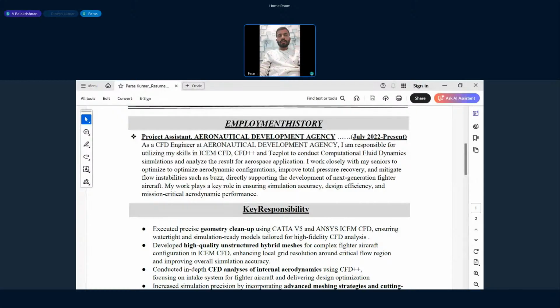Yeah, it depends. It mainly goes to the mass flow rate, like whether the engine wants more mass flow rate or less mass flow rate. So sometimes when the engine demands less mass flow rate and we are giving more, it leads to spillage drag. Okay.